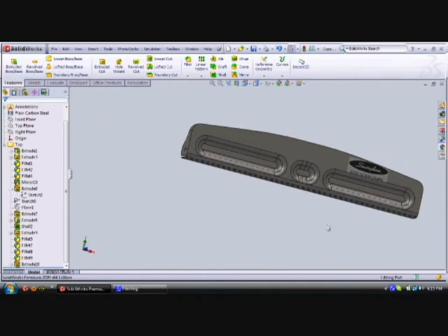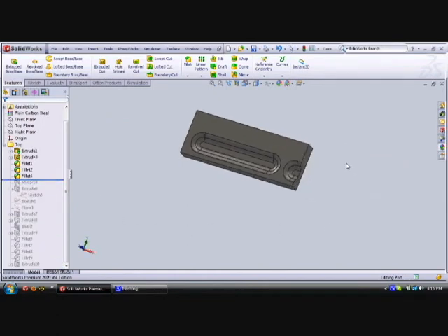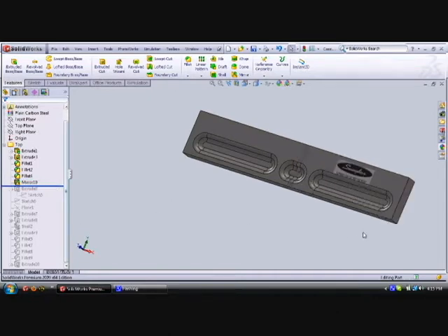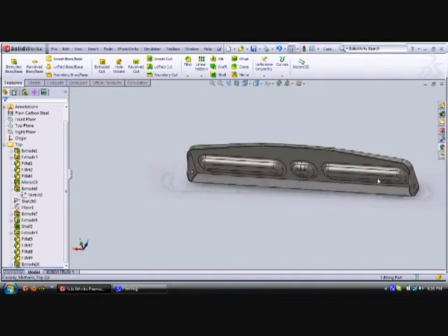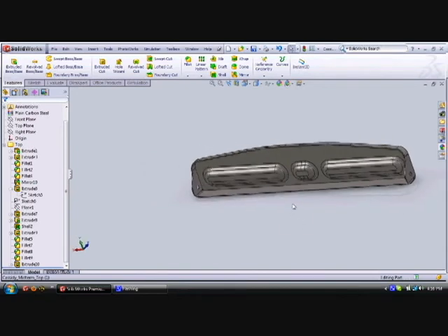Here we see the top of the 3-hole punch. To create it, I used the symmetry of the object to only design half of it and then mirrored it across the right plane to produce the rest of it. I then shelled out the back of it to create a uniform thickness of the entire plate.